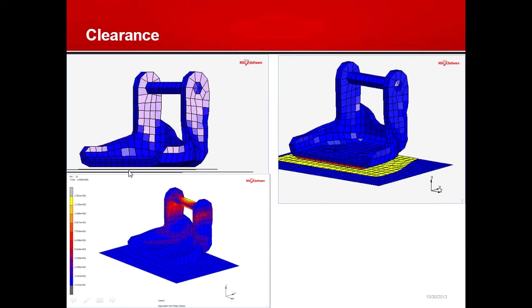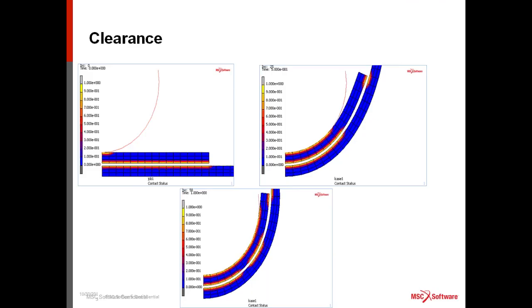So you could reduce the thickness, generating a clearance, and if you say include that clearance, we will use that in the simulation, and it will be as if the bodies are truly in contact with one another.